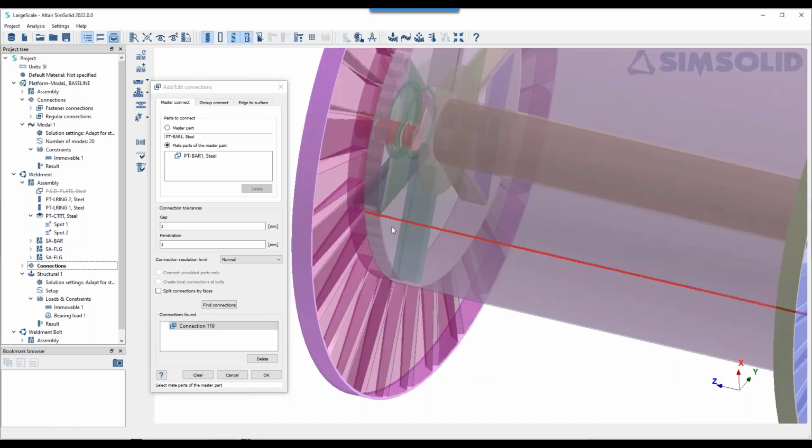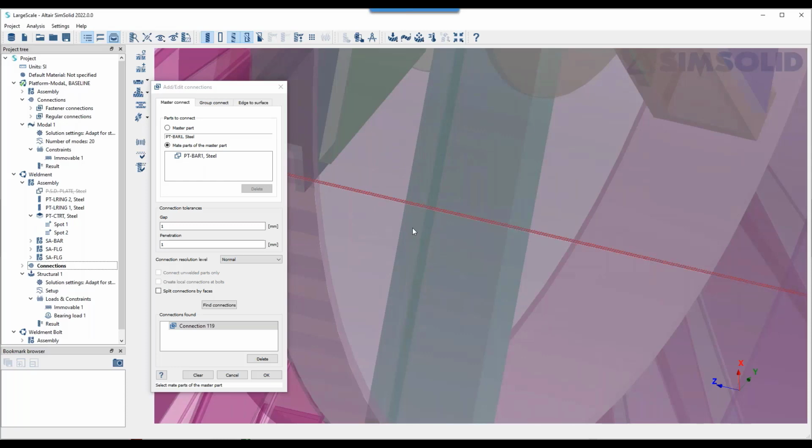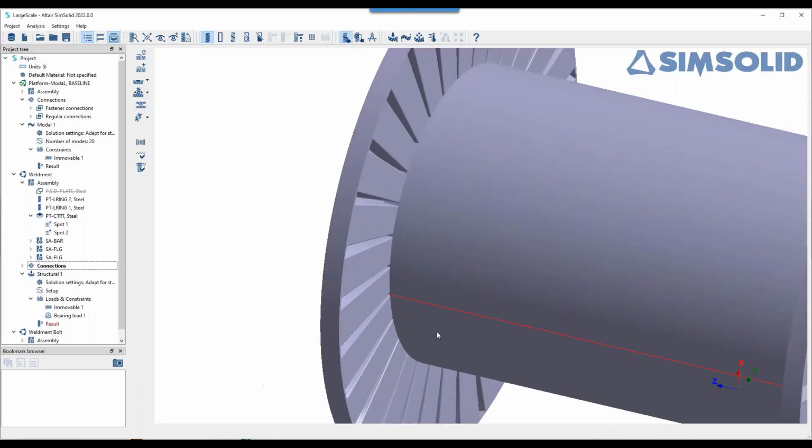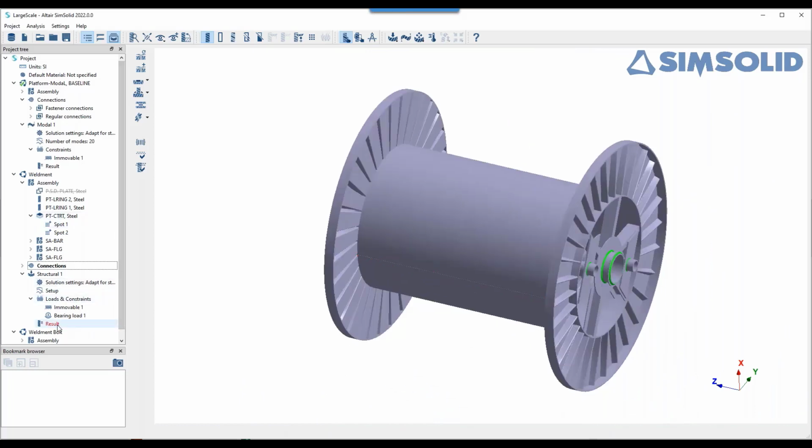and there you go. See, this is almost impossible inside Inventor and Nastran. You cannot create a contact between a single component. The contacts only apply to assemblies. In here, we can apply a contact on a single component like this one. So now I think we are okay, and we go and press run again.